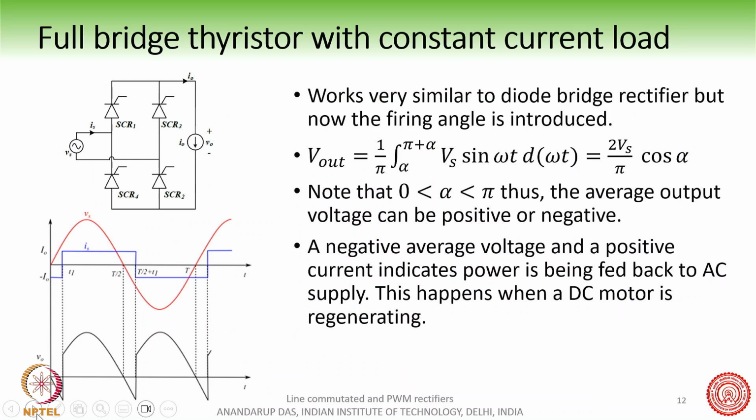Now, when you have a large motor load, of course, then this RL load we replace with a constant current load, right? The reason being that the time constant of this RL load is so high as compared to the 50 hertz AC sinusoidal impressed voltage or the source voltage. The AC waveform alternates every 20 milliseconds. The time period is only 20 milliseconds.